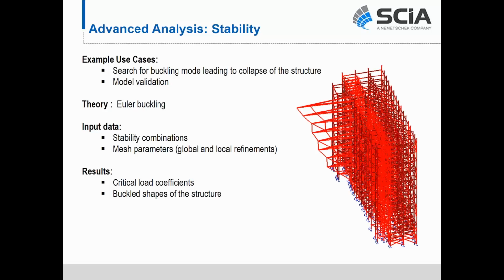And so you can find out very quickly if that's under 1, that structure's buckling under your regular load is a failure. And if it's over 1, you can see how safe and stable your structure is. And so you can see very easily on a large structure, where do I need to add bracing on plates, where do I need to add bracing?